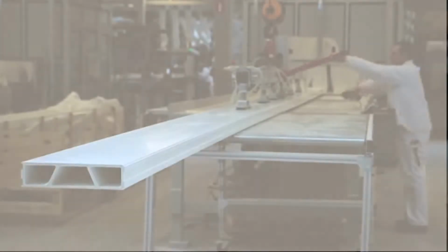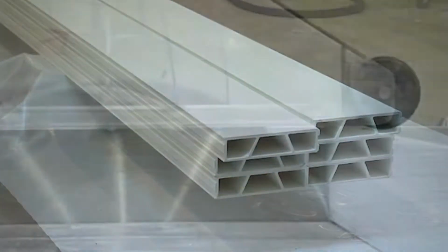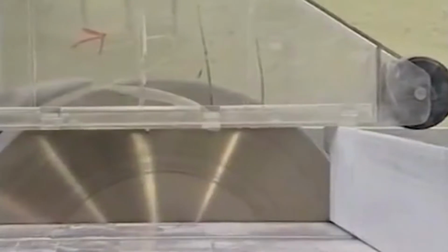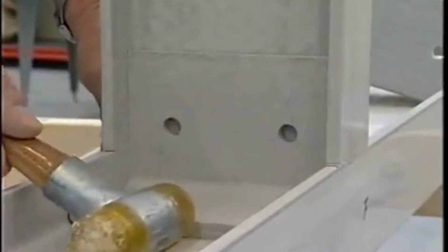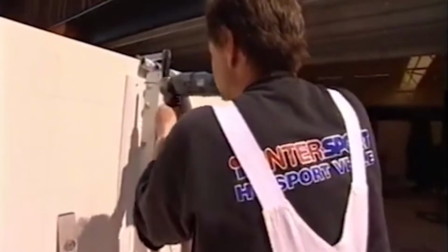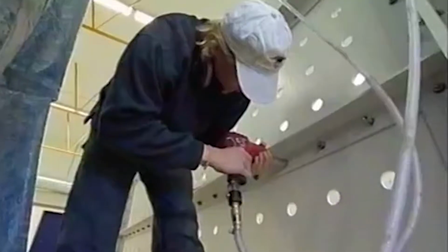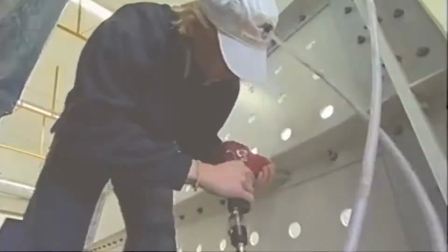The finished pultrusion continuously emerges from the die as a completely cured thermoset. Pultrusions are then cut into manageable lengths, typically 20 to 40 feet. Pultrusions are cut, drilled, machined, and shaped much like wood. PFRPs can be managed on-site by carpentry trades. Pultrusions can be connected to each other using conventional hardware or with high-strength adhesives.